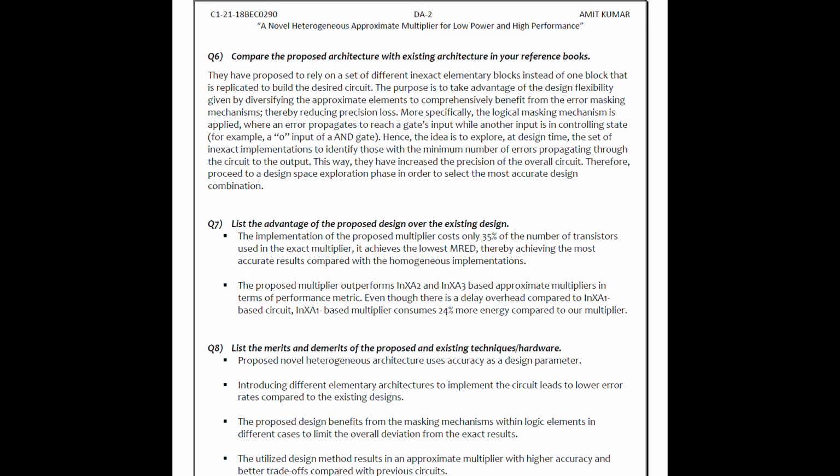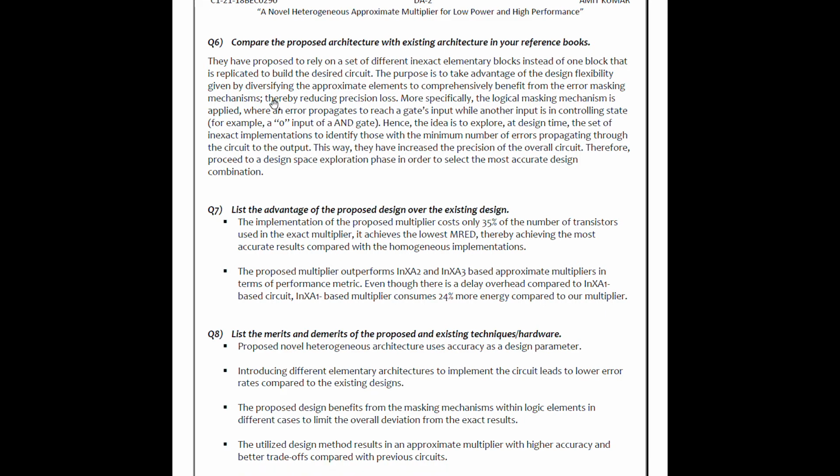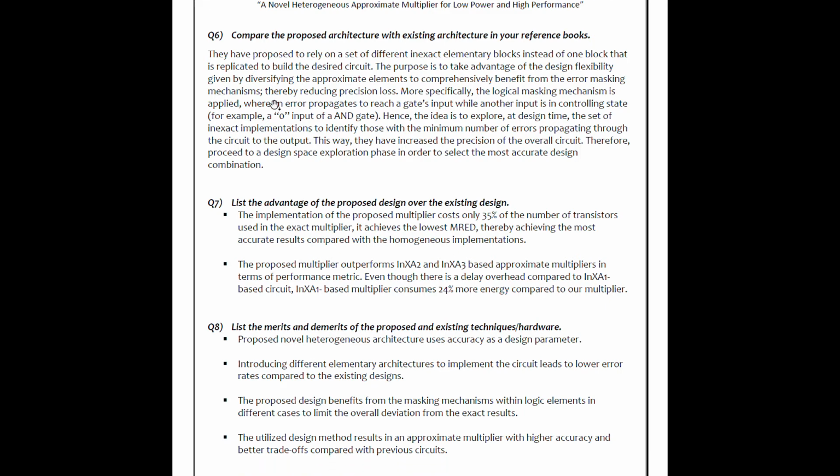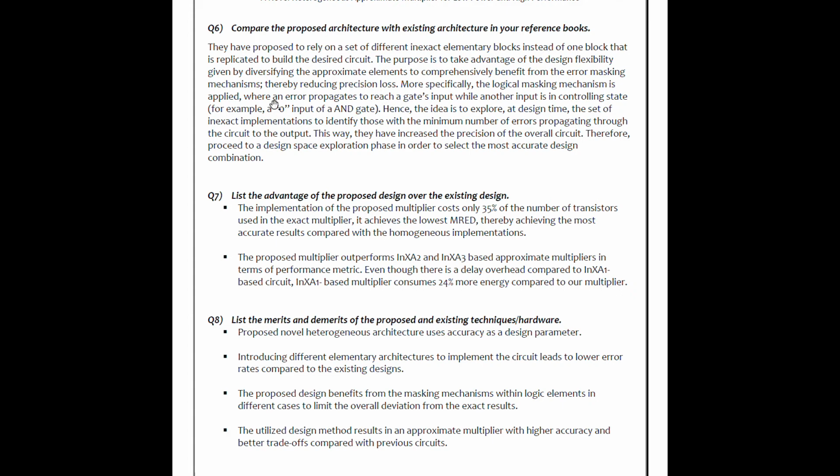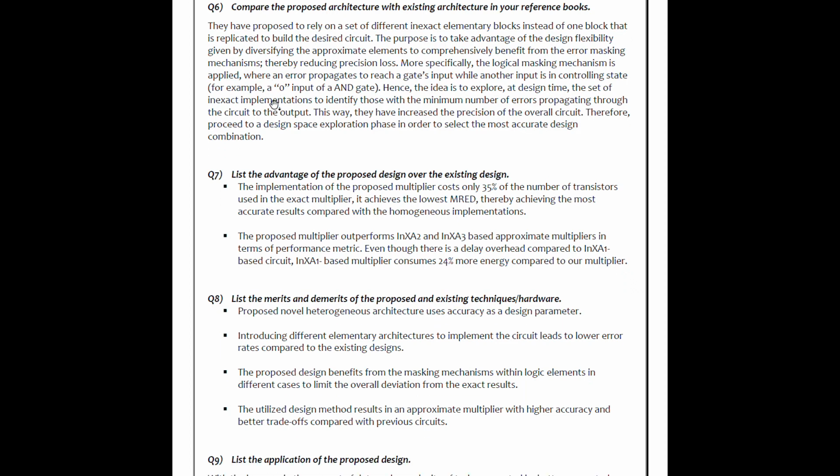More specifically, the logical masking mechanism is applied where an error propagates to reach a gate input while another input is in the controlling state. Hence, the idea is to explore at design time the set of intact implementations to identify those with the minimum number of errors.